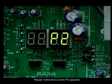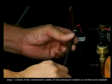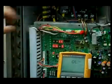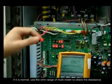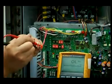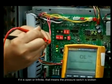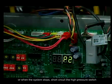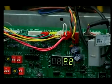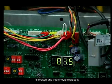Repair instructions when P2 appears. Step 1. Check if the connection cable of the low pressure switch is correct and reliable. If it is normal, use the OHM range of a multimeter to check the resistance. If it is open or infinite, that means the pressure switch is broken. Or, when the system stops, short-circuit the low pressure switch. If the malfunction disappears, that means the pressure switch is broken and you should replace it.